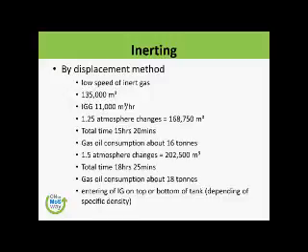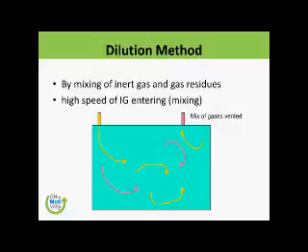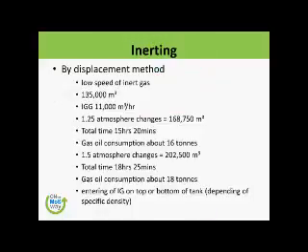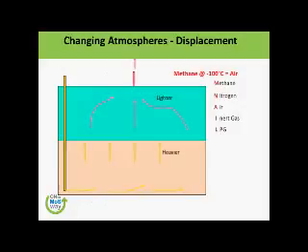So anyway, what we try to do is achieve the targets for the environment. We do not compromise on safety. So even if this process has to run for 4 days, we will be happily doing it. So, entering the IG at the top or the bottom of the tank depends on the IG density. If it is heavier than air, then of course use the bottom line. If it is lighter, then you push it from the top and you take it out from the bottom.